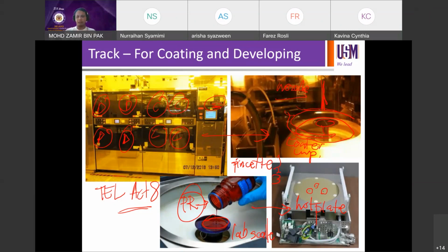So it's very complicated. For example, if you talk about the hot plate down there, when you send a wafer using the pin set, an 8 inch wafer, the pin set has to be calibrated exactly following the size of the wafer. When you send it to this hot plate, before you place it on the hot plate, 3 pins will come out here. These 3 holes are actually 3 pins. When you send the wafer by robot, to help you appreciate the process, the 3 pins will come out from under the hot plate.